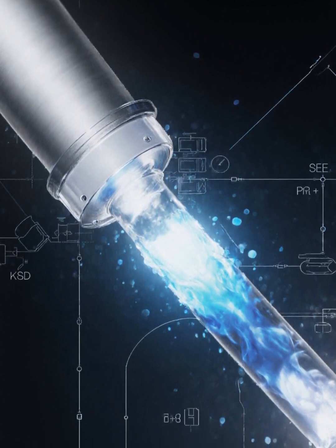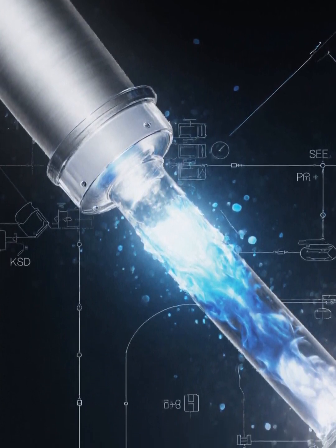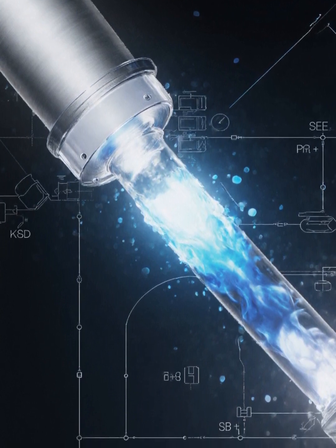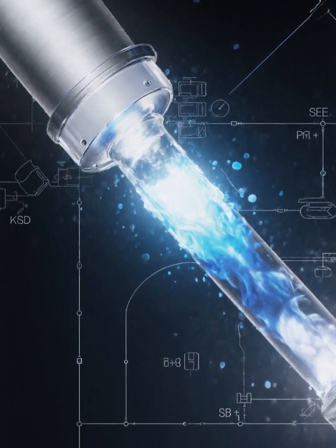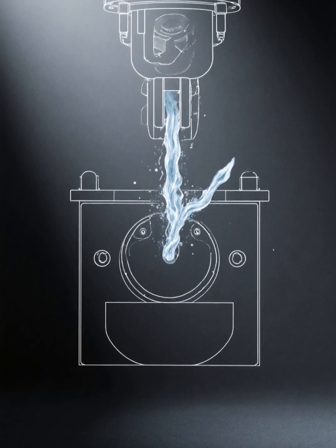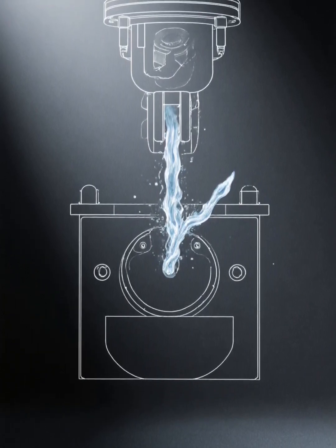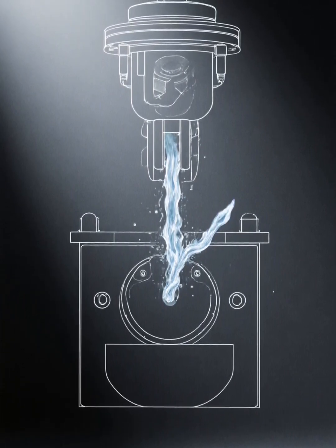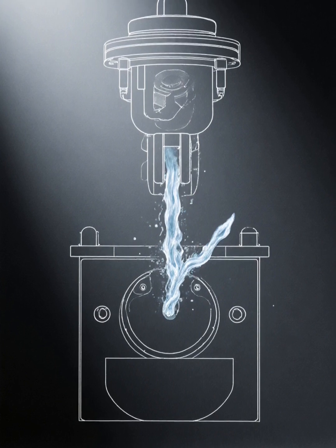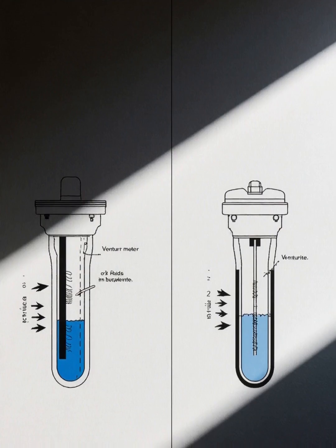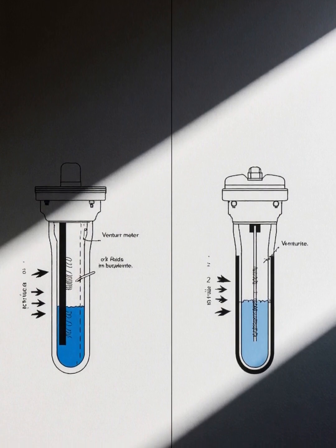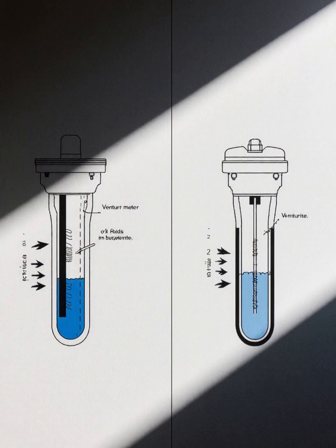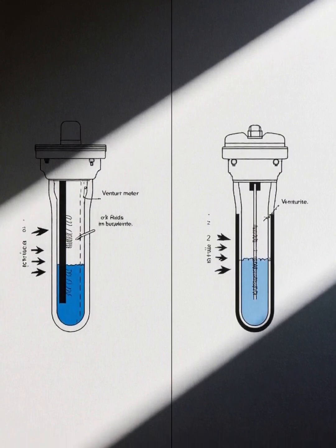The Venturi meter uses gradual contraction, leading to less head loss, higher accuracy, and higher cost, making it ideal for long-term use, while the orifice meter uses a sharp-edged plate, causing greater head loss but lower initial cost, making it better for budget-conscious applications with easy plate changes for different flow rates, although with lower precision and downstream pressure recovery issues.